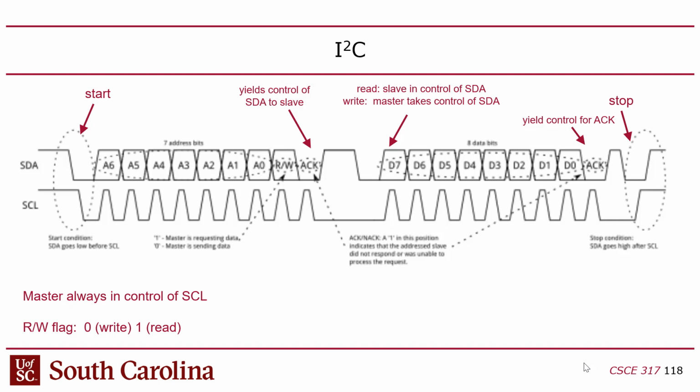It gets handed off. I send something, you send something. So it's only half duplex, unlike SPI. Remember, SPI was full duplex, wires going in either direction. Here there's one wire, only one entity can talk at a time, but that's okay, because remember in SPI, we had two wires, but we only used one of them at a time, right? What a waste. Whenever you did a transaction, one of the wires was just dead anyway.